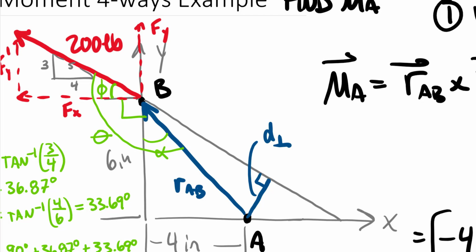All right, so as we look at this system, what we see is basically we need to continue this 3/4 slope. Okay, let me label that on here, that our line of action has a 3/4 slope. It's actually a negative 3/4 because of the direction it's going, just like our force vector had a 3/4 slope.